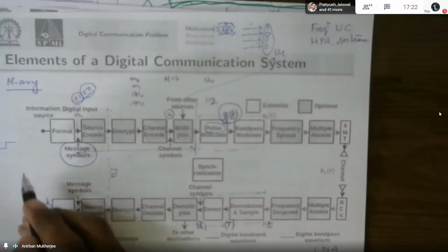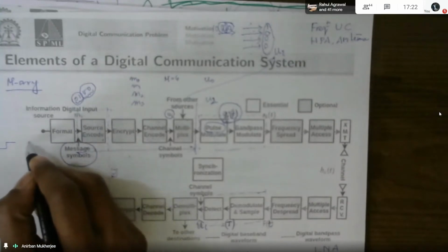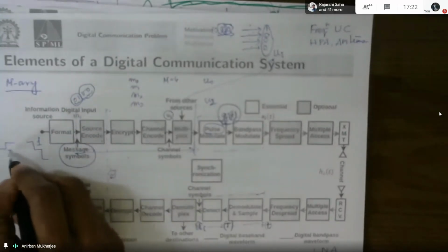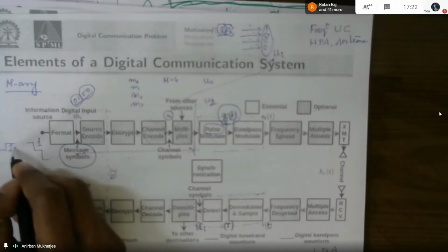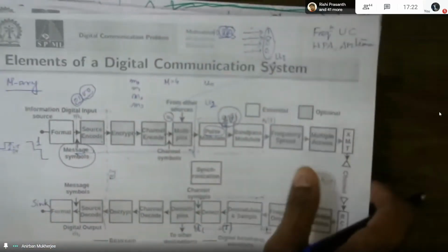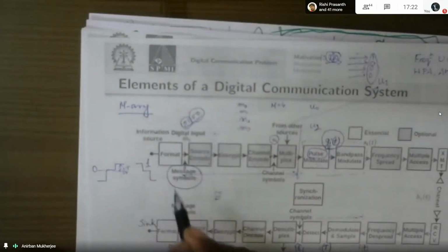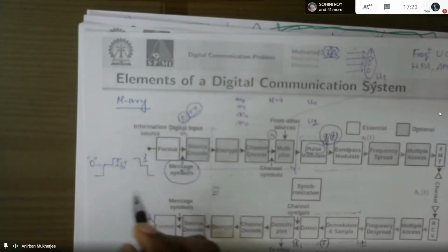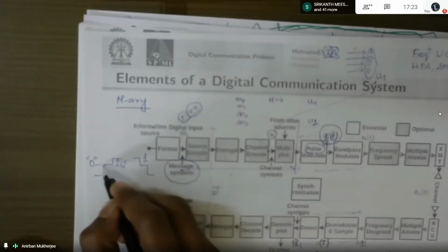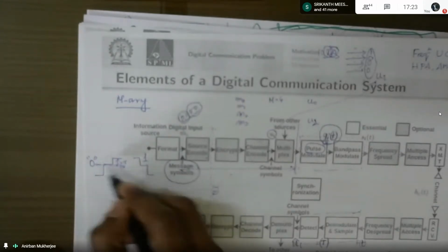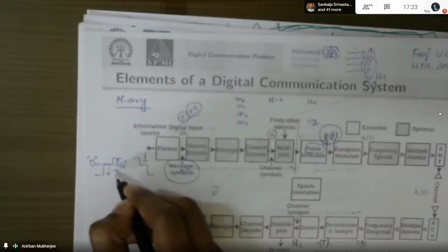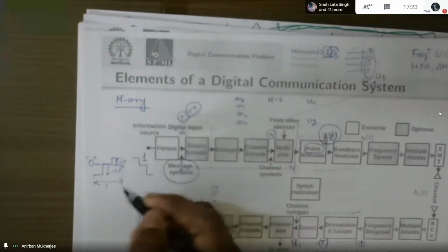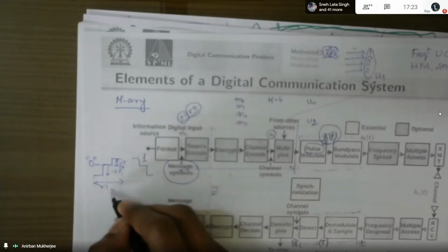Say I am saying this pulse modulation, say this is my 0, and say this is my 1. Say this is my 0 volt, this is some sort of say 2.5 volt. So it is a logical bit stream. In the pulse modulation, what you are doing, say logical 0, I am defining as an electrical signal where it is ground 0 volt, this plus 2.5 volt, this minus 2.5 volt, and this duration you are taking say 0.1 millisecond.